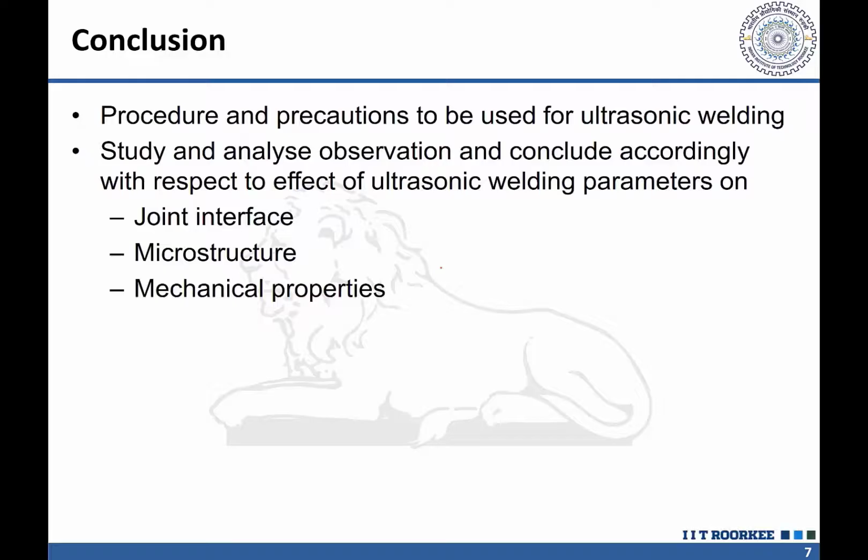So considering the various aspects related with the kind of thinning which is taking place, or the kind of interfacial bonding taking place, or the soundness of the joint or the kind of metallurgical transformations which are occurring at the ultrasonic joint interfaces, or the load carrying capacity of ultrasonic weld joint needs to be analyzed.